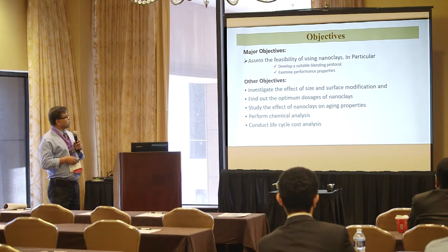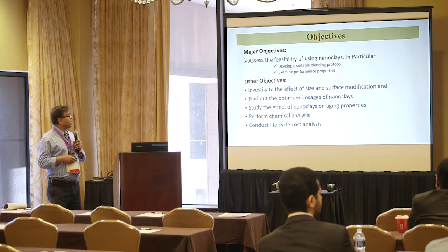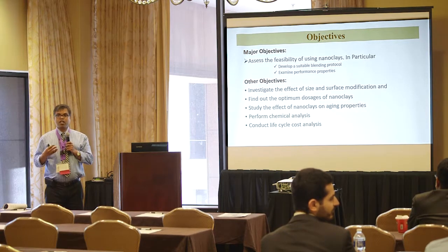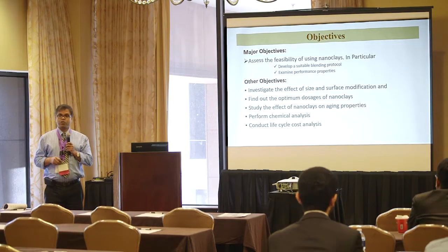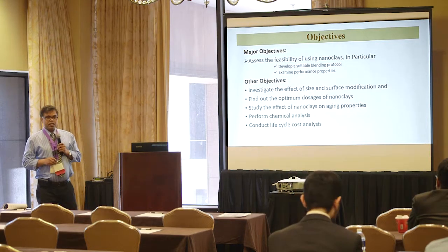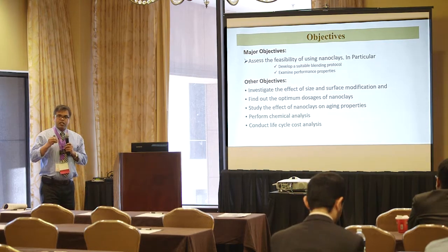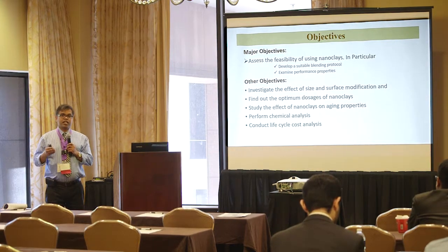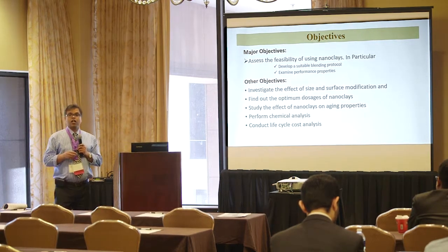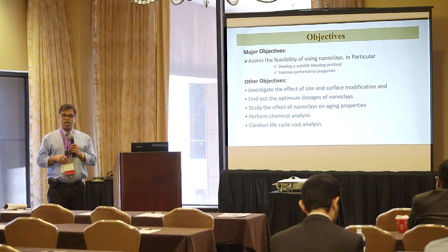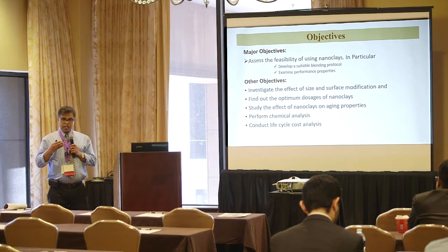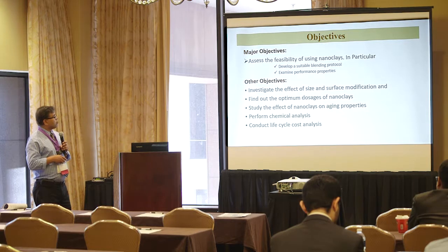So again, the objective is to see the feasibility of nanoclay. The first thing, which is a challenging job, is to develop a protocol for how to blend nanoclay with asphalt binder. Because this is not a traditional liquid or any kind of anti-stiffness additive, this is nanoclay. It is montmorillonite clay. We need some combination of temperature, rotation, as well as time, how much time we need to spend. So one of the objectives was to find a good blending protocol, followed by performance properties.